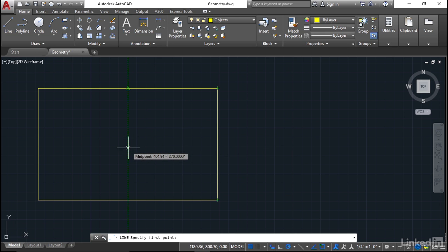And now these are also tied in with my object snap tracking. So what I'll do is I'll hover over that midpoint again there. And as I come in this time, can you see that I get an intersection? Now that intersection is my object snap tracking kicking in with my polar tracking as well. The polar tracking we'll discuss in a moment, but you can see there with polar tracking on, which it is on the status bar, if I click on that intersection, that's where my line starts from, which is the dead center of my rectangle.